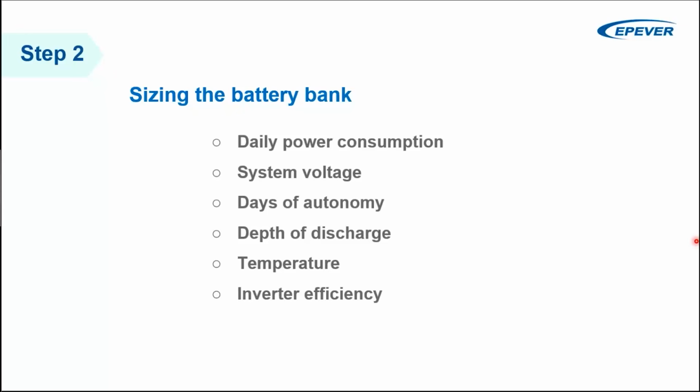And the inverter power also plays a role in selecting the battery bank. It's one of the factors in determining the size of the battery, because not every inverter is compatible with every battery. So this is the step of selecting the battery, but at the same time you should keep an eye on what charge controllers and what kind of inverters are available in your market. If you decide to use a 48 volt system voltage, then the inverter must be available for you in the market to purchase and use.